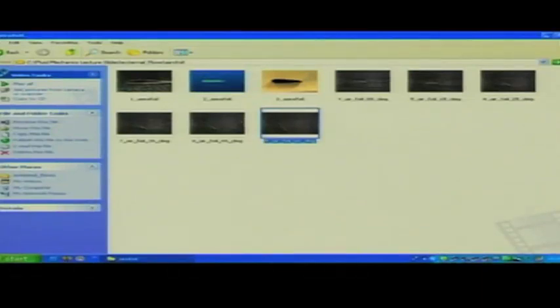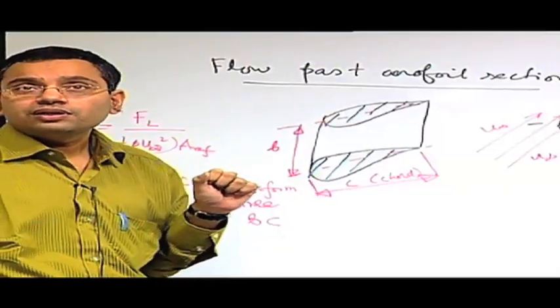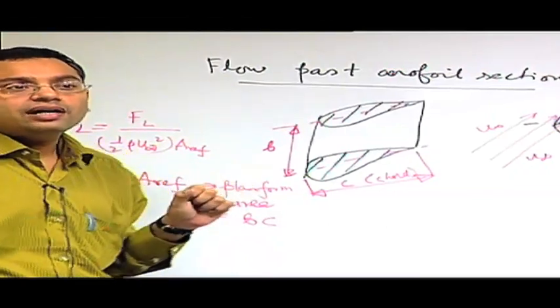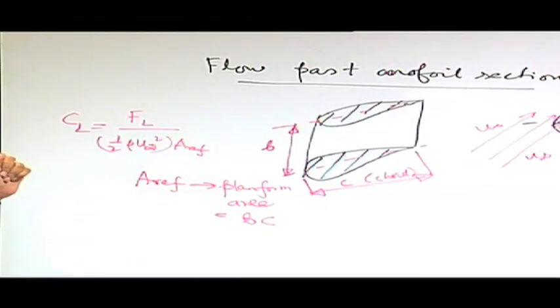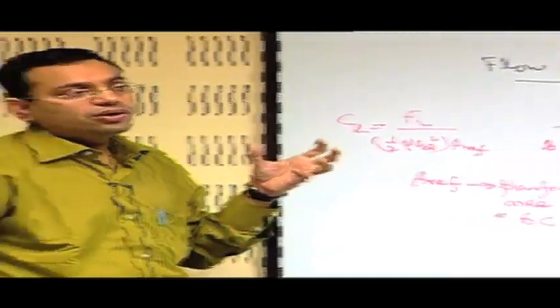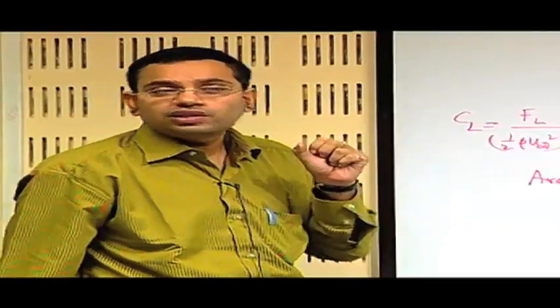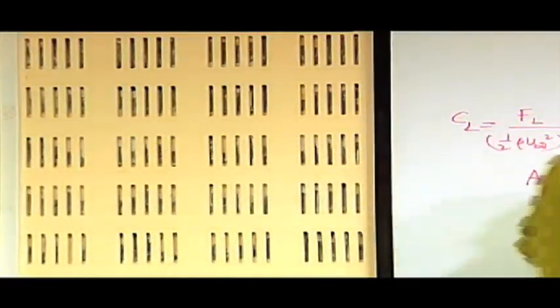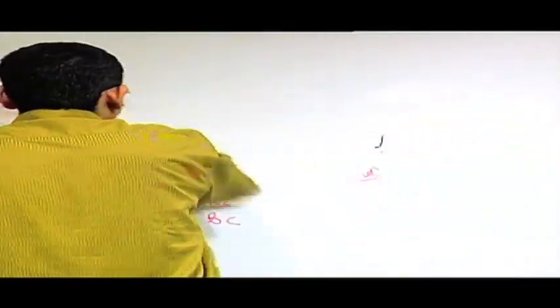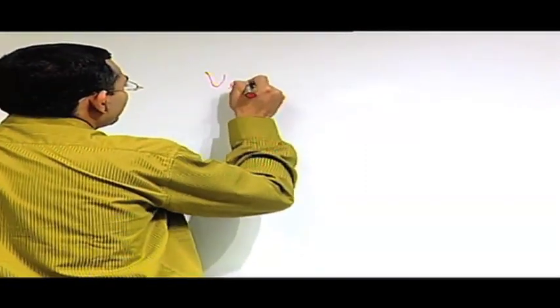Now if we go on to study the flow past different shaped bodies: till now in the boundary layer theory we have considered cases with high Reynolds number. The reason is quite obvious, that only if you have high Reynolds number may you apply boundary layer theory. But there may be interesting cases when the flow is very slow, or the relative motion between the fluid and the solid is very slow, that is also flow past the body. Therefore let us quickly see the consequence of very low Reynolds number flows.